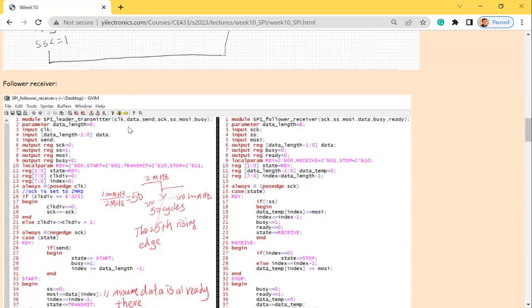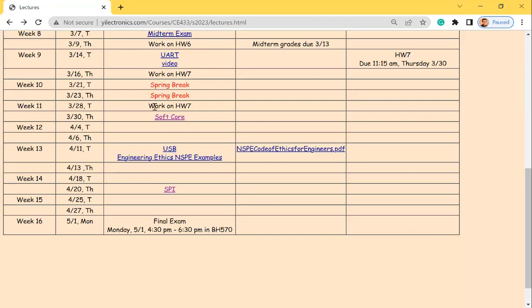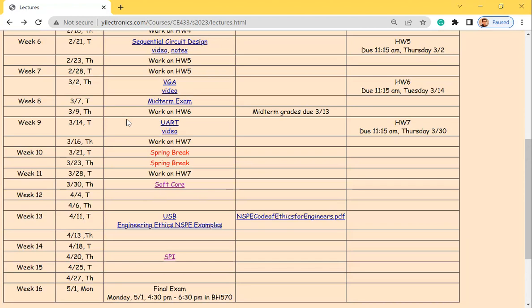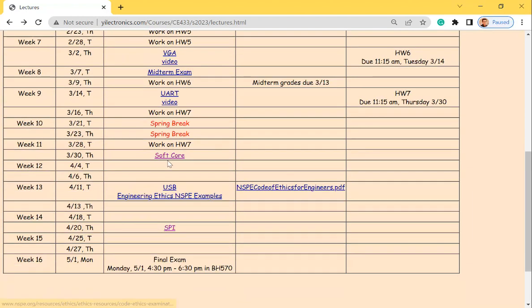And if you can write a digital module or digital design for SPI, you can put it into the top module as one of the modules, along with the core. So you can put a core in it, it's going to be the CPU of the microcontroller, and you put an SPI in it. Then you can have the pins similar to UART, like RX, TX, right?